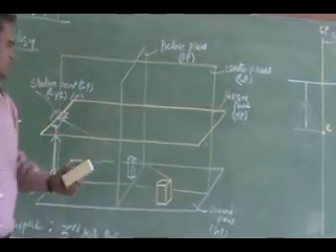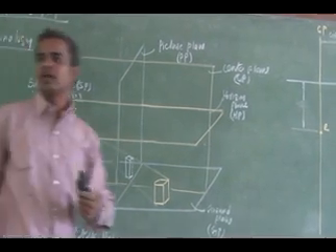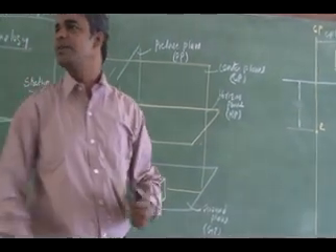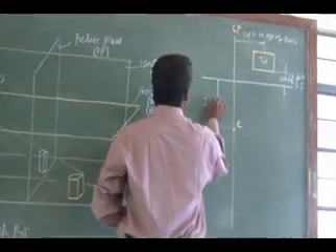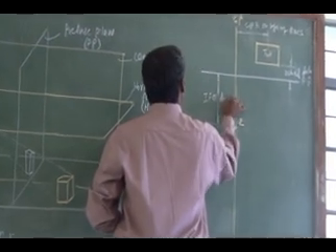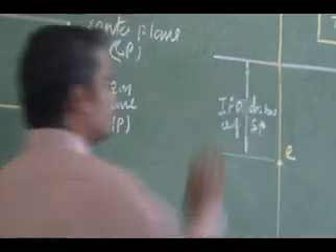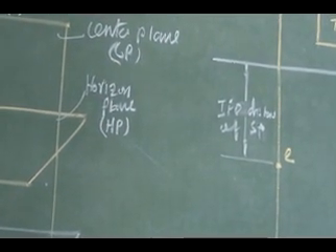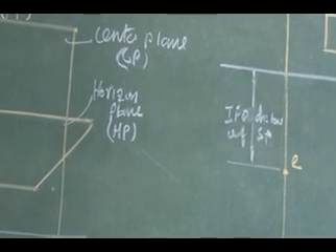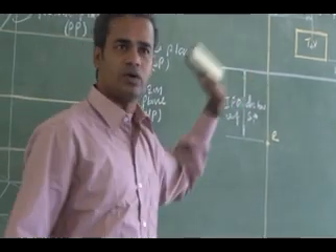In front of distance. What is this distance? It is the station point's distance from the picture plane. It is the in front of distance of the station point from the picture plane. So it is the in front of distance of the station point, or E. Station point is equal to E, right? So this is about my top view details. These details will be given in your problem. Try to draw the layout, right?